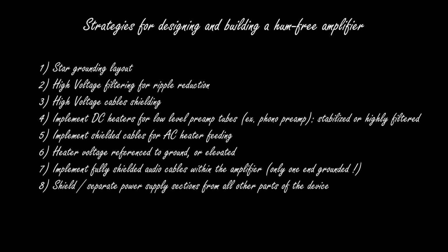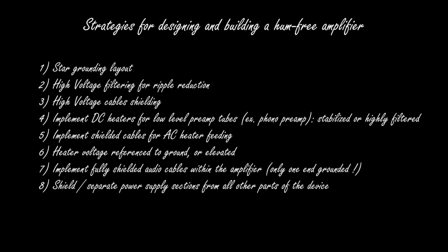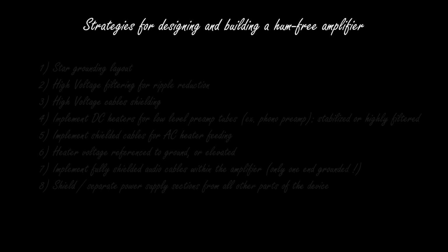I didn't say before, but maybe it's obvious from what I said before, it's very important to shield all the power supply sections. Ideally, it would be great to implement a copper or aluminum shield between all the power supply sections and all the rest of the circuit.